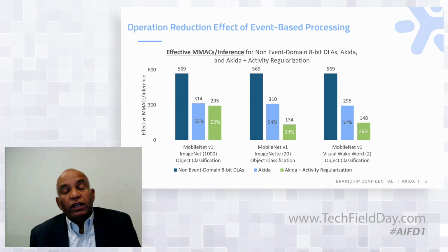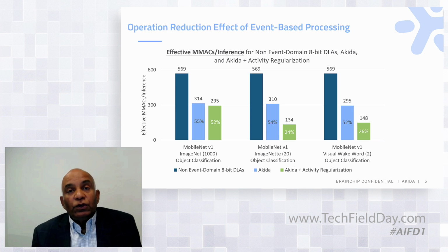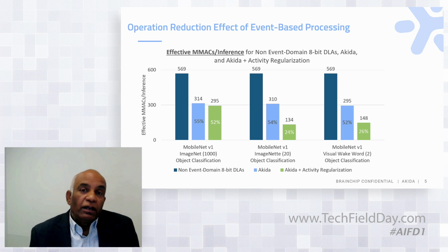Like we talked about camera frames, if you give me camera frames, I will create events out of them. But there are different types of cameras that generate the events directly. These are called dynamic vision sensor cameras, DVS cameras. Rather than sending you 2 million pixels, they send you only the address of the pixels that changed in intensity, just like our eye. These are called artificial retinas. So there are devices like that.